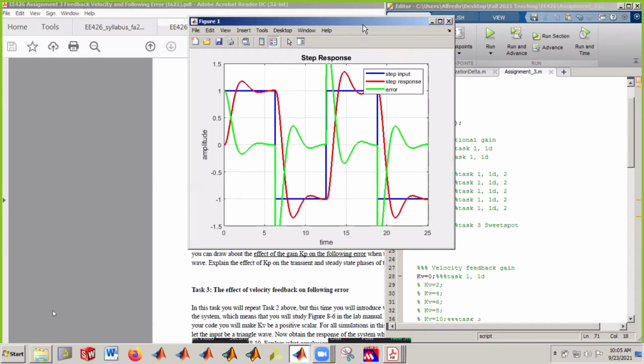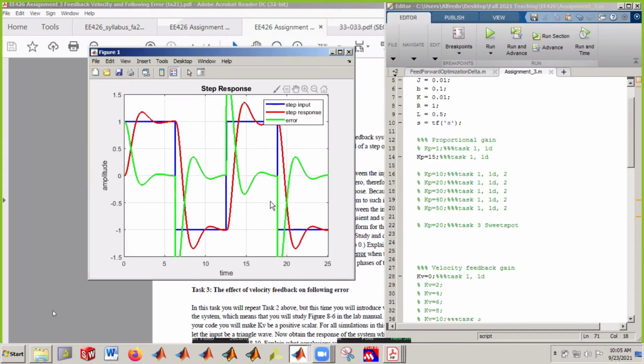All right, so this is the square wave response. You may notice something here. Notice how the overshoot is smaller here than in the other particular instances of time where the input changes too. This is due to the initial condition, right? I mean, this starts over here at 0, and it only has to go from 0 to 1. So that is why you don't get that much overshoot.